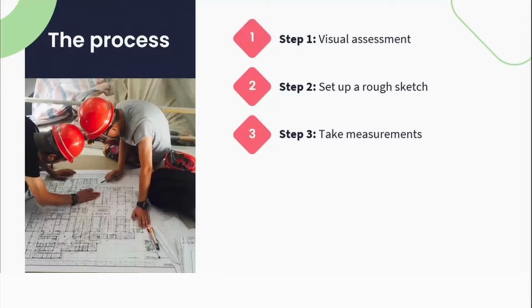For example, if I've measured the length of a wall from right to left, you're then going to add the exact dimension onto your wall on your sketch as a width from right to left. Go around the space systematically, working with your walls around the perimeter and then moving into the center. And I usually do this in a clockwise format so that I remember exactly what I'm doing. It's a systematic approach. I don't want to get lost or stuck while conducting these surveys. As you know, they can be time consuming.